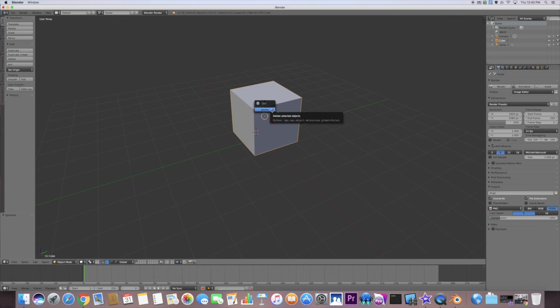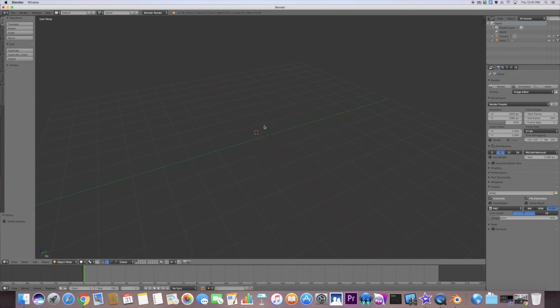And it'll say, okay, you want to delete? Click delete, and that object will disappear. Now, in order to create a new object, along the left side here, you'll see these tabs. The one that says create will allow you to create new shapes. These are called primitive objects. Primitive objects are starting objects for more complex shapes.